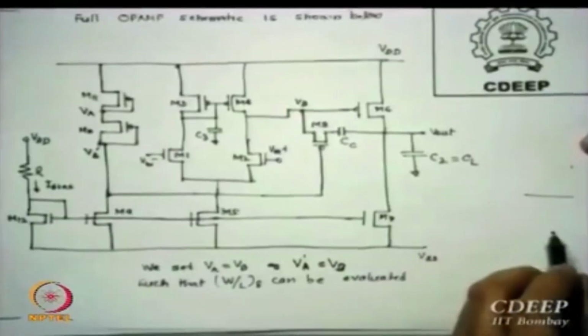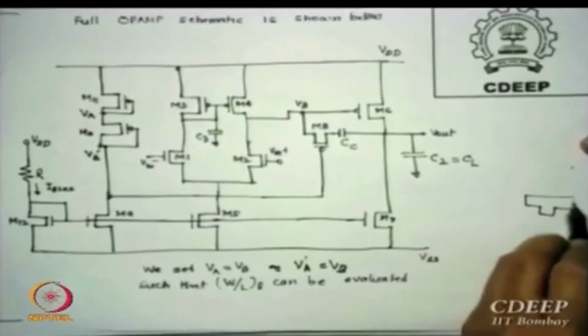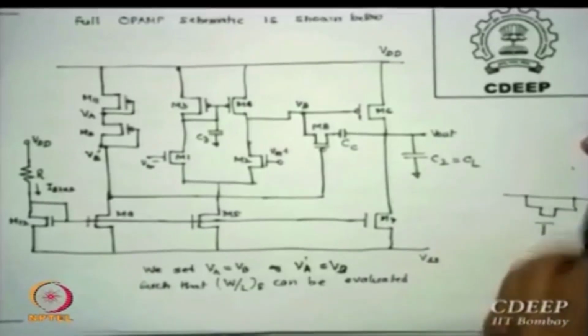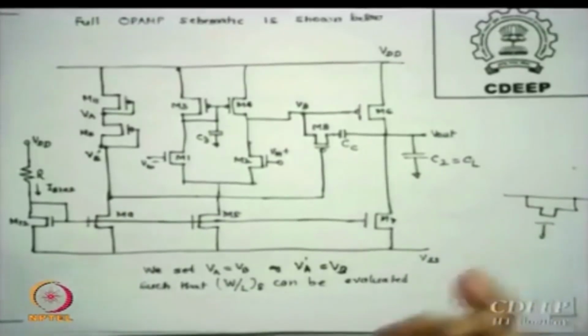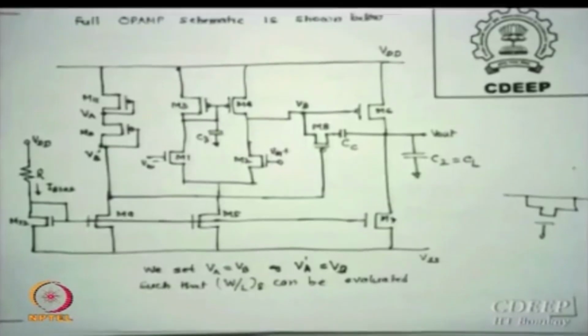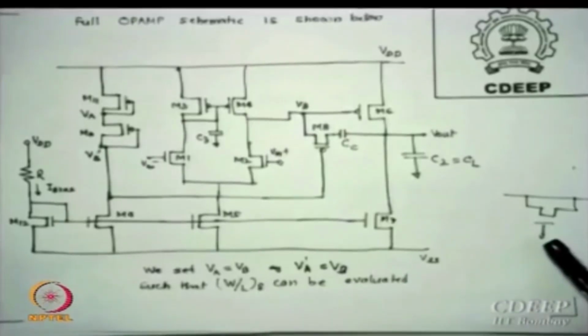You have to create a MOS capacitor right there. How do you make a MOS capacitor? Now see how a MOS capacitor is made. Got it? Connect source and drain, okay, and ground them, and apply bias from below, so this VGS gives this capacitance. So you actually create CC by a MOS capacitor, okay. Please remember, this voltage is also very important because CC will be a function of this voltage.